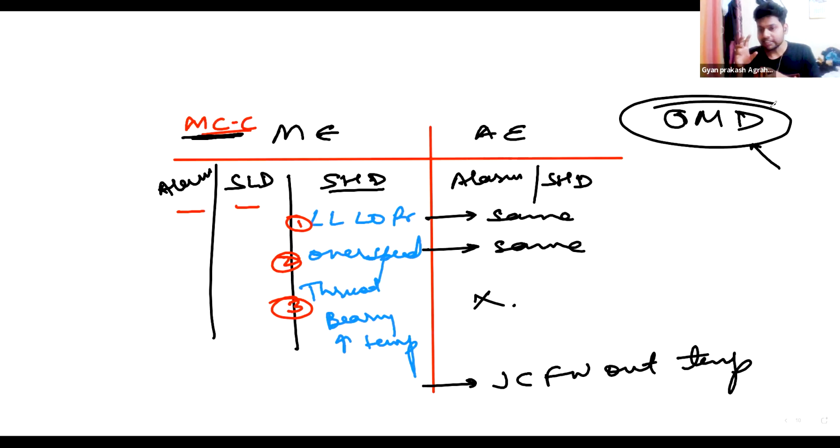Is it related to a region of very high temperature because of bearing failure or lubrication failure? See, if you have two parts rubbing together without lube oil, it can cause a hot spot. So you don't want a hot spot. That is the first reason to create an explosion. And that hot spot is the reason for the creation of mist.